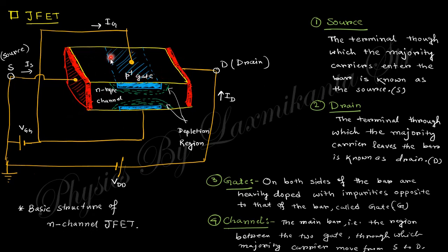And this region, if it is rectangular, then upper and lower, otherwise if it is cylindrical, then all around, will take a highly doped opposite type. This is n type, so there will be doping of p plus. Okay, trivalent doping in high density. Plus means high concentration. When the doping concentration is high, it is denoted by the plus symbol.